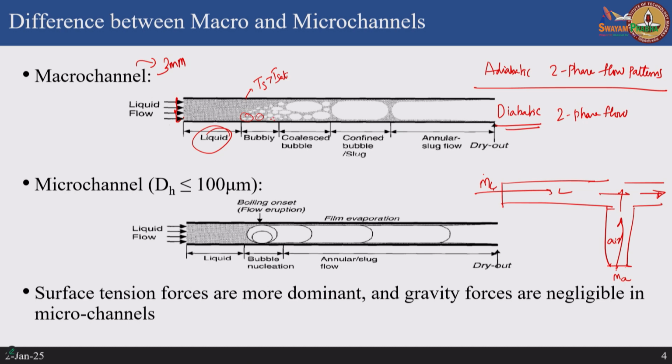Now, usually on a large diameter tube, these vapor bubbles will start emerging from the lower part of the tube, because of the buoyancy they can detach and rise up, and they progressively go downstream, and there is also a flow of the liquid here. It is not a quiet fluid, there is a fluid with a given convective velocity, and therefore these bubbles are advecting downstream, and as you continuously supply heat with a uniform heat flux, the surface temperature is increasing along the length of the tube.